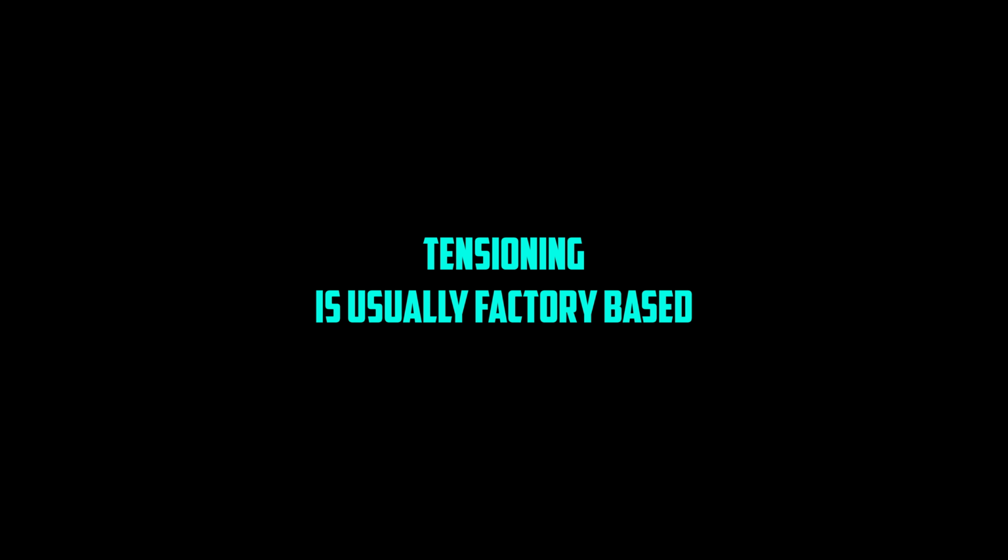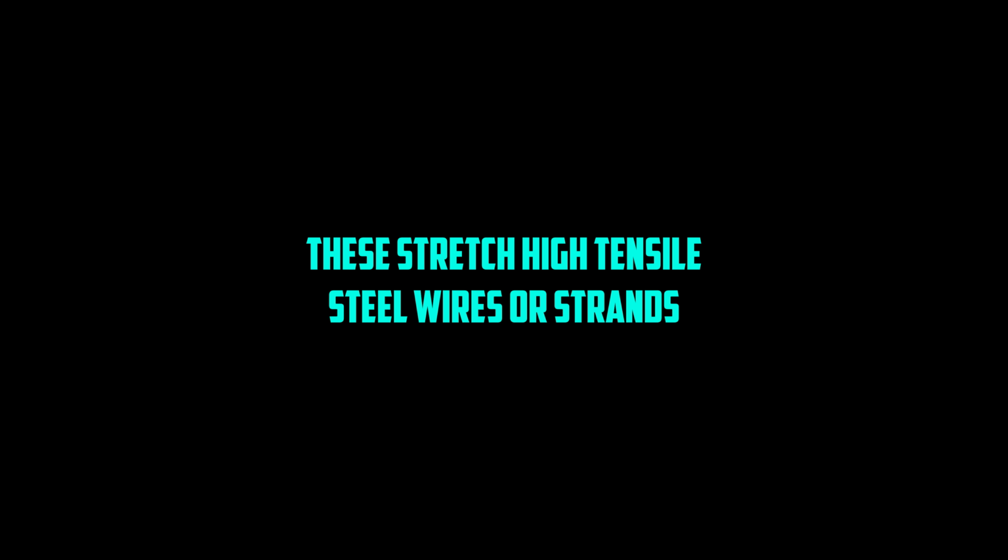Yes. Pre-tensioning and post-tensioning. Pre-tensioning is usually factory-based. You stretch high-tensile steel wires or strands in a mold, then pour the concrete around them. Once the concrete hardens, you release the tension. The bond between the steel and concrete holds the compression in.